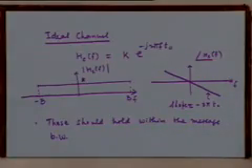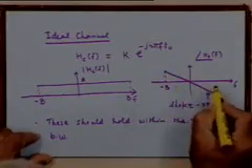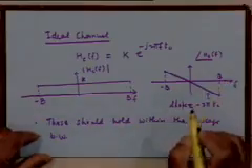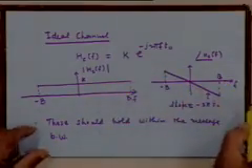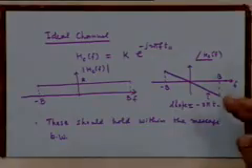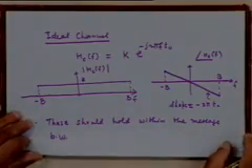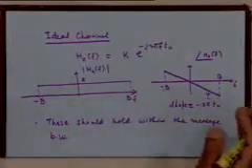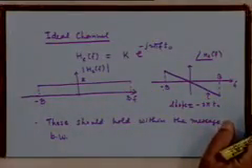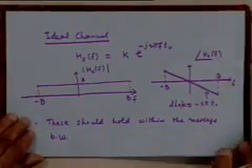It may or may not be, because the signal does not have any frequency components there, so it won't bother us. Similarly, these linear phase characteristics should hold between minus b and plus b. After that, if it becomes slightly nonlinear or something else happens to it, it's not a straight line after this, it doesn't bother us very much, because the signal does not have any components in that frequency. Is that clear? So an ideal channel in a practical situation would be one which has these kinds of characteristics within the message bandwidth at least. Is that okay? Good. Any questions?